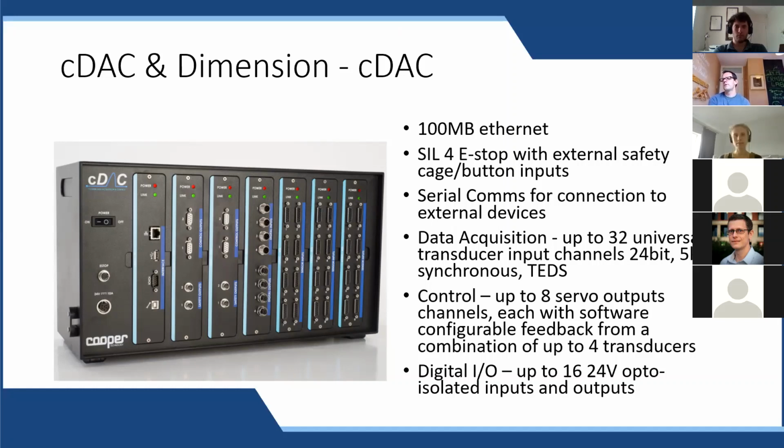And then data acquisition, we can have up to 32 transducer input channels, 24-bit, 5 kilohertz, all with TEDs. So when you plug this transducer in, you actually straight away have all the calibration and the setup of the amplifiers and everything included in the plug of the device. So there's no manual, no user error involved in that part of things.